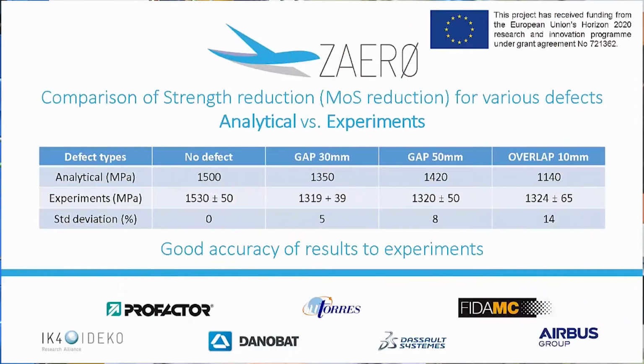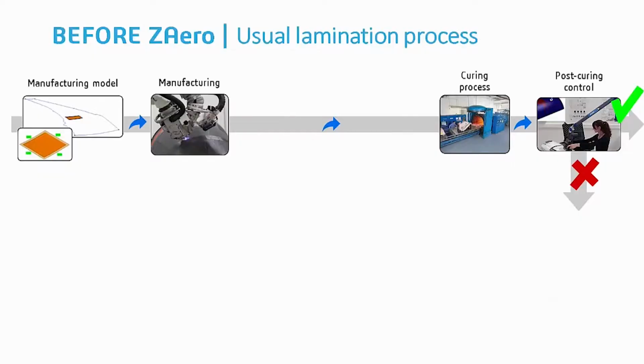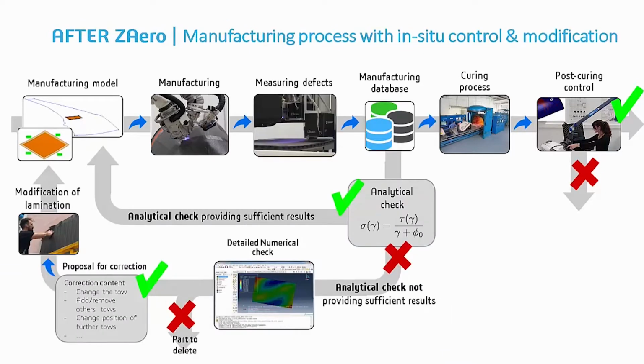Typically, the second approach is used for defects highlighted as being of concern by the first method, or where the defect is large enough to have varying stresses or is in a zone of varying layup. The safety margin calculated for each defect is stored in the manufacturing database for later use by the decision control tools. Further work is needed to improve the empirical calculations and to extend them to cover more types of defect.